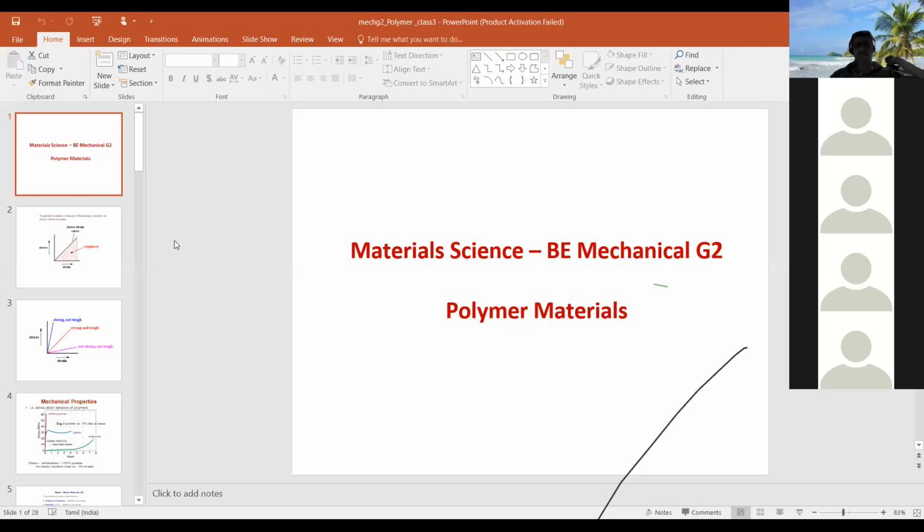Third course outcome is polymeric materials. So far, what you have seen is the crystalline nature of polymeric material, right? No polymer is 100% crystalline. Part of a polymeric material is amorphous, so generally we call all polymeric materials semi-crystalline polymers. In fact, you can have 100% amorphous polymer, but it is very difficult to reach 100% crystalline polymer.